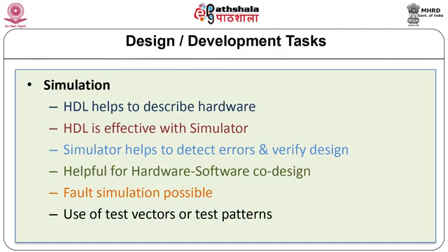In many CAD tools, the simulator can handle hardware description as well as the software to cope with the hardware-software co-design approach. At this level, it is possible to carry out fault simulations as well. It checks the faults or imperfections in fabrications using a set of test vectors or test patterns. This task can be automated with the help of automatic test pattern generators.